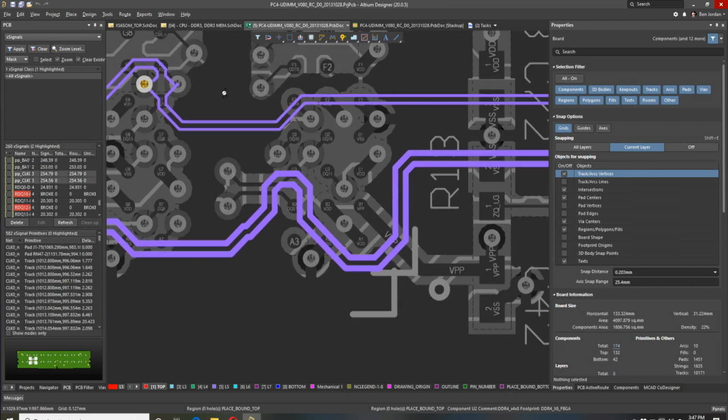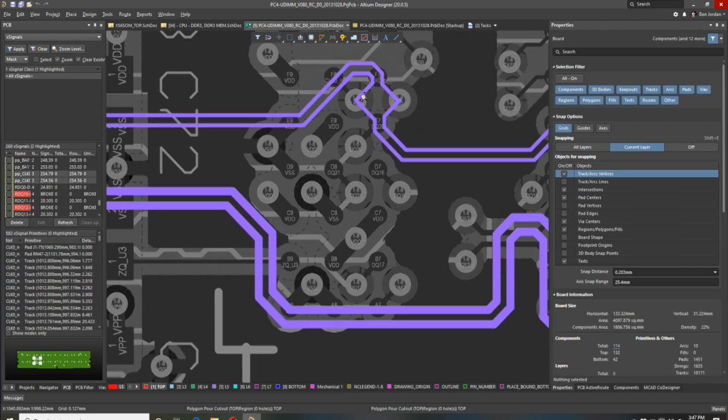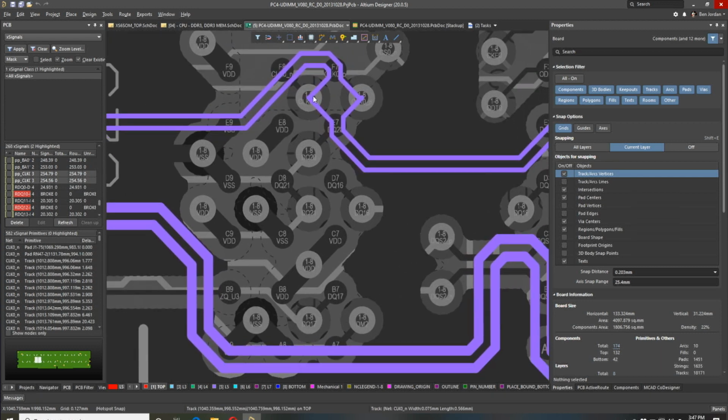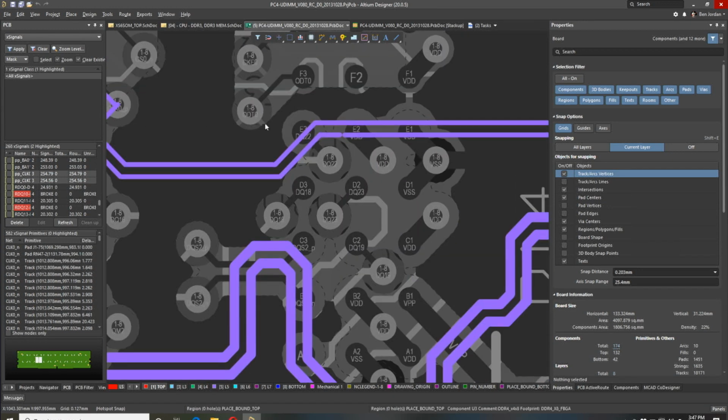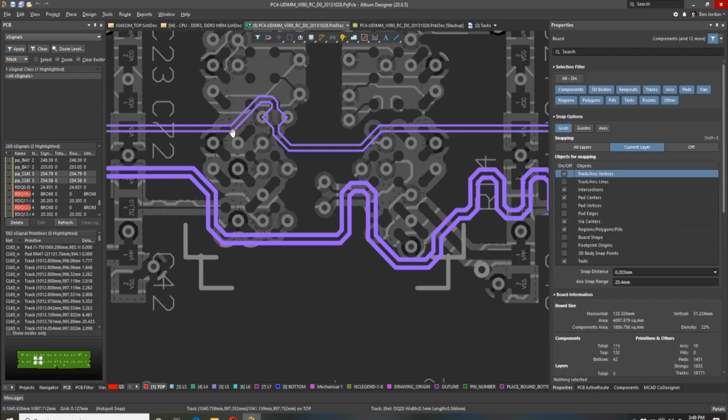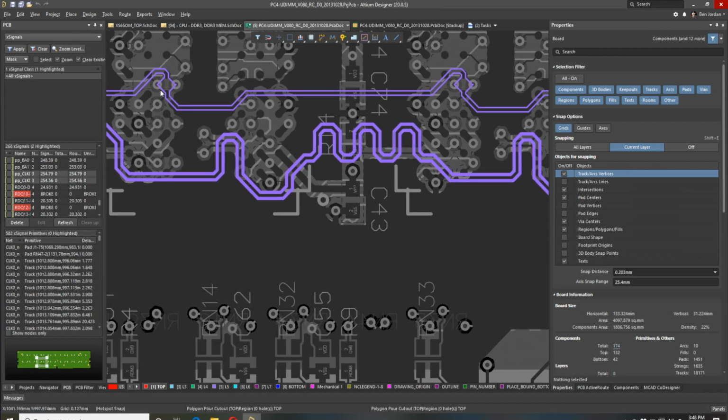Fortunately for a design like this too, these modern DDR chips have pretty good on-die termination and other features we can use to equalize things even within the package of each device, which is nice. So there's the next connection through, and between each of these, this is exactly the same trace structure. So even if you didn't have an automated length tuning capability like we do, you can do the first one and certainly use copy-paste. And this comes back to grids and planning. Always use really good, carefully chosen component placement grids that are a multiple of the BGA pitch you're dealing with.